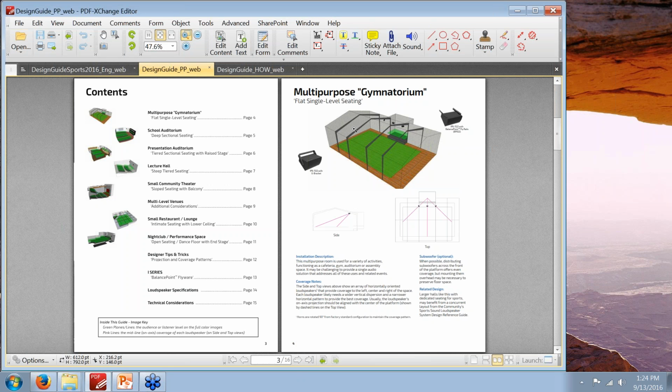You're likely, at least for localization, going to want to have a sound system to reinforce a stage and dramatic performances. And then you're going to have a sports system, whose speaker coverage is optimized for covering the bleachers. Everybody's kind of hearing everything at time 0, but it's preferably, I'd say, 2 systems most of the time to properly address it and localize the sound if you're having graduation or commencement on the stage. But then, a couple days before, there was a basketball game and the stage curtains were drawn and you're using the overhead system shown in the sports design guide.